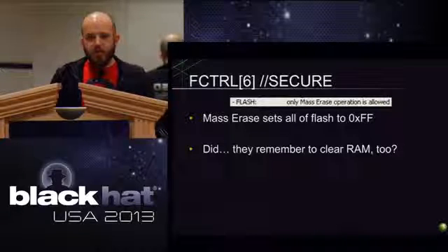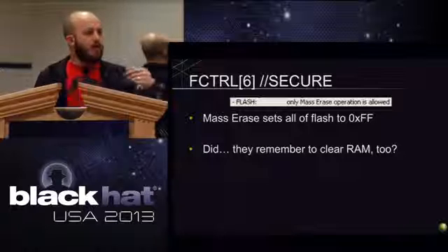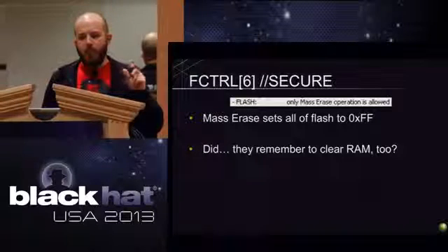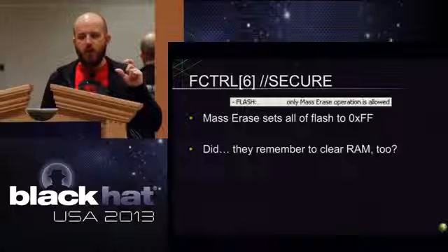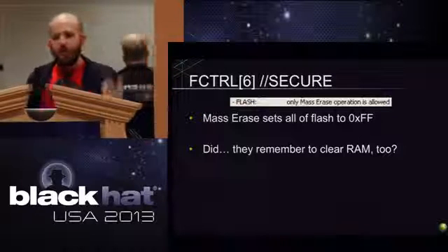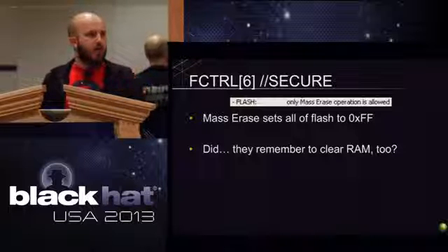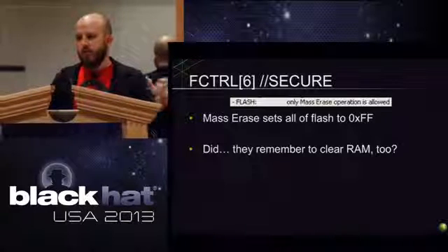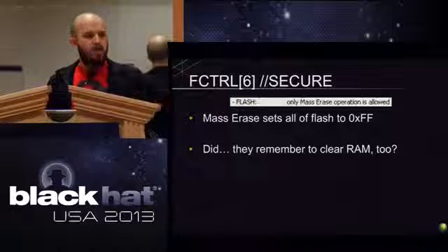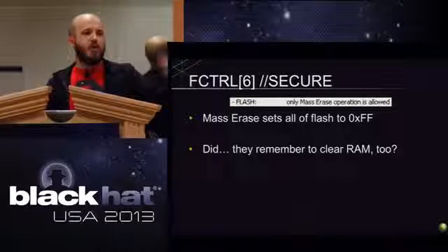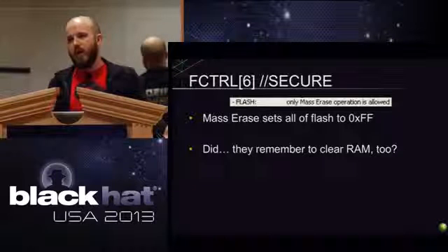The way to unset that. So it's not, again, a permanent flag, right? The way to unset that kind of stuff is to hit it with a mass erase, so that you wipe out the code that is setting that in the first place. So in the first 30 or 60 cycles, what's normally happening is that there's an instruction that runs that sets this bit and says turn off the debugging interface. Pre-boot phase ends, and then the debugging interface does not come up.